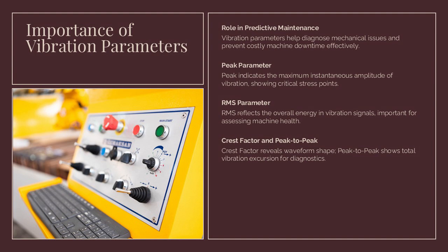Each parameter serves a unique purpose. Peak indicates maximum instantaneous amplitude, RMS reflects overall energy, peak-to-peak shows total excursion, and crest factor reveals waveform shape characteristics. Together, they form the foundation for accurate vibration diagnostics.